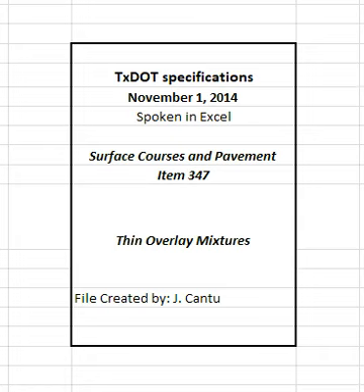Prevent splattering of tack coat when placed adjacent to curb, gutter, and structures. Roll the tack coat with a pneumatic tire roller to remove streaks and other irregular patterns when directed. The engineer may suspend paving operations until there is adequate coverage.